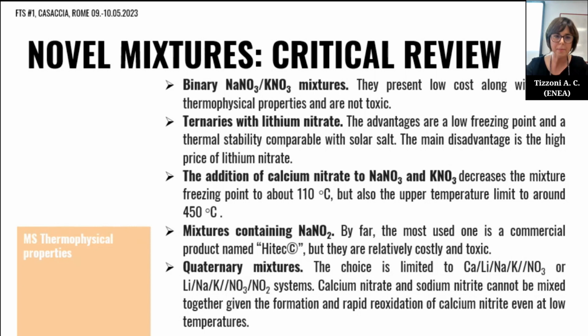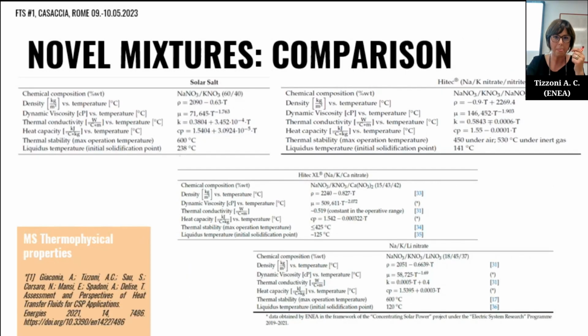And the mixtures, as we already said, containing sodium nitrite are relatively costly and also toxic. And regarding quaternary or quinary mixtures, the choice for now is limited only to the one containing calcium and lithium. But this is because calcium nitrate and sodium nitrite cannot be mixed because there will be a formation and rapid reoxidation of calcium nitrite even at low temperatures. So the mixture is not homogeneous.